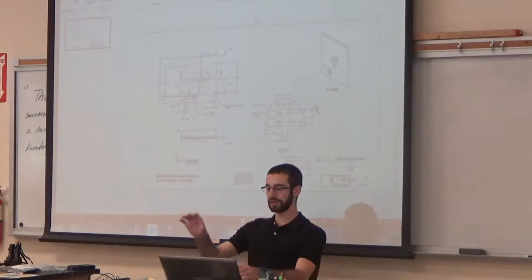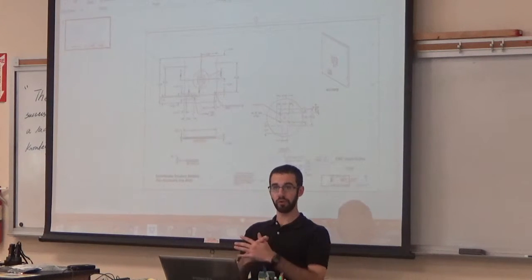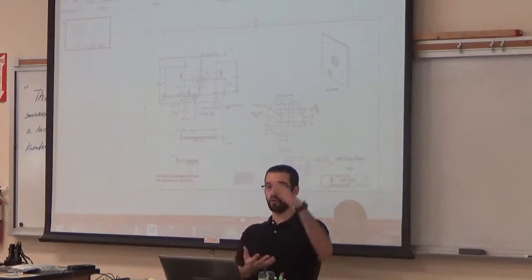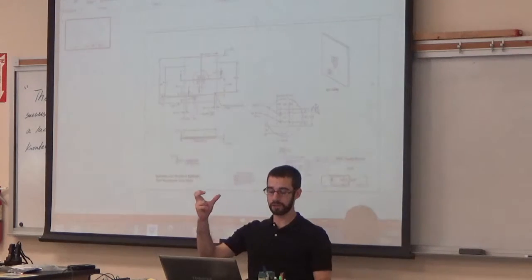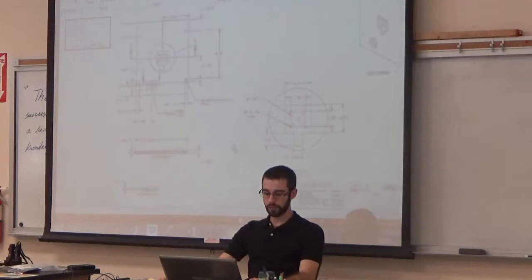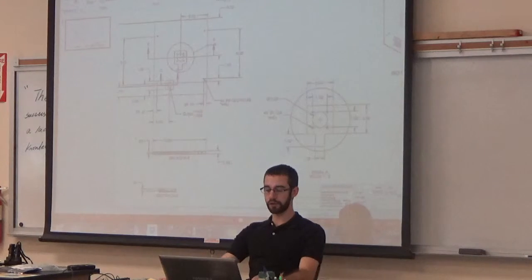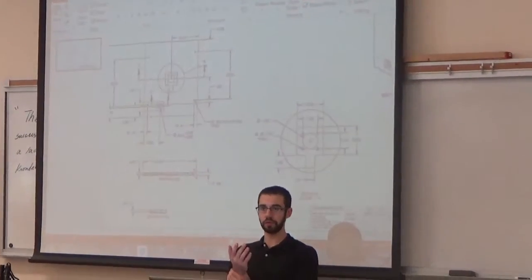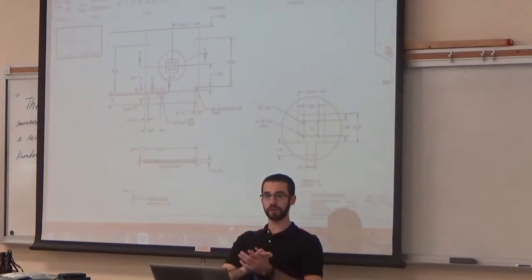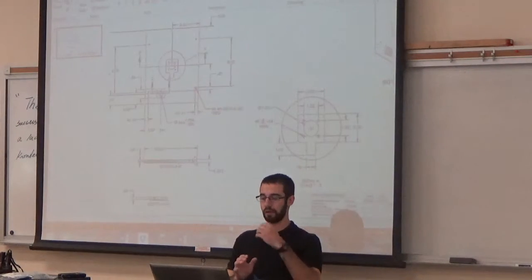I can show it to you, but basically what I'm doing is I'm calling out where the screw holes are, where the cuts are, the overall dimensions of the part, where my brackets are screwing into. So in here you'll see this view right here. Basically, that's a cross-section view. So if you have a more complex part, you're going to have more images.